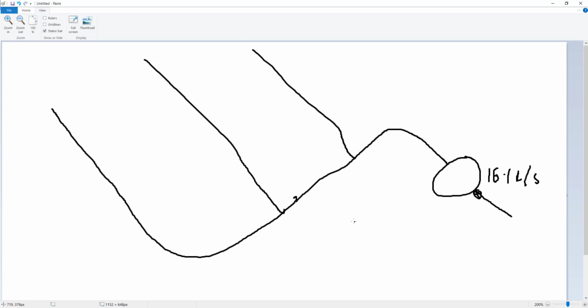And what we're going to do is place some SuDS features around the catchment and control the flow using those. The intention is to reduce the size of the pond at the outfall. So the first thing would be the placement of the SuDS features. There is an option within InfoDrainage called deluge analysis, which is useful in determining where low spots are and where water may naturally accumulate, and that would obviously be good places to put our storage structures. But one way or another, we're going to have to derive where our storage structures are. In this example, we're going to place a swale roughly here, and then a permeable pavement up here.